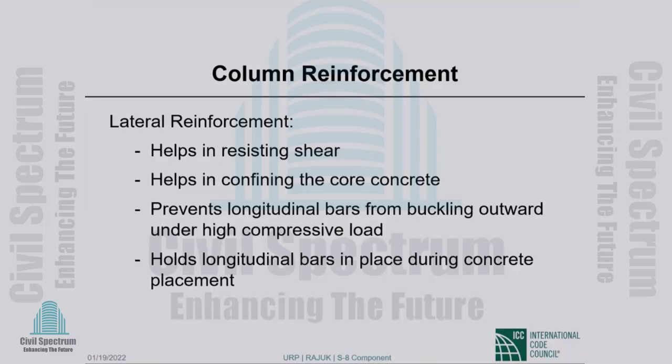Those are the ties, and they do other things. One very, very important thing that the lateral reinforcement does is to confine the concrete, particularly if the lateral reinforcement is closely spaced. And in seismic applications, that is an extremely important role.